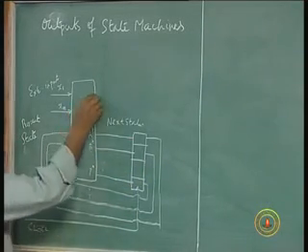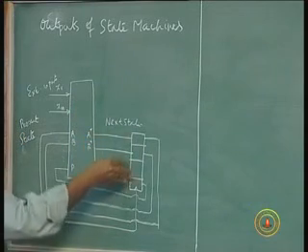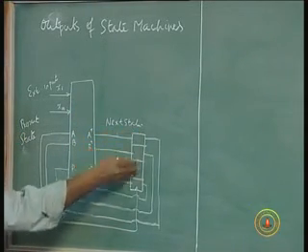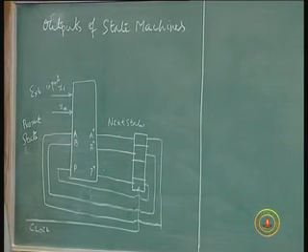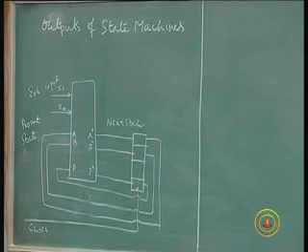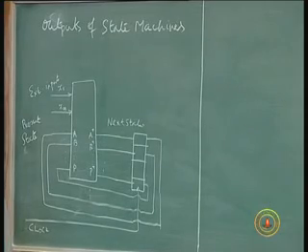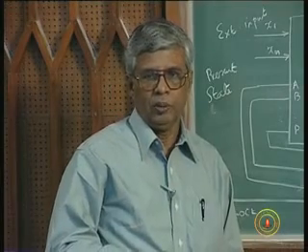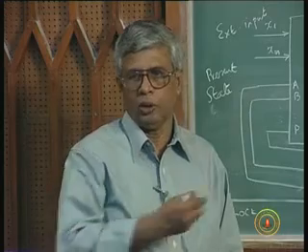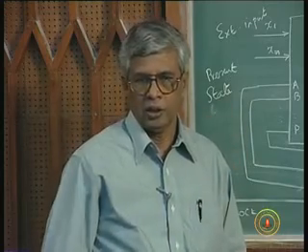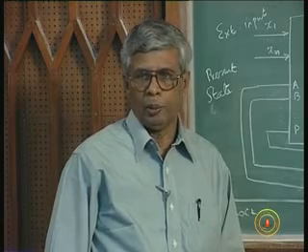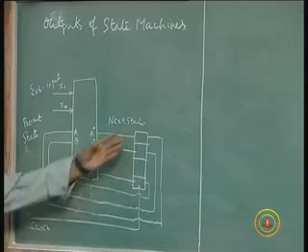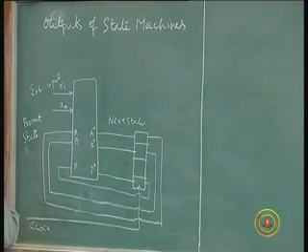In addition, this itself can act as outputs in the case of counters, for example, the state of these flip-flops, that is the counting sequence through which the counter goes, will act as an output. For example, if you want to know the number of counts that has lapsed till now, you can look at the counter states. Suppose you want to count the number of people getting into a room. Anytime, the number of people in the room is given by the state of these flip-flops.